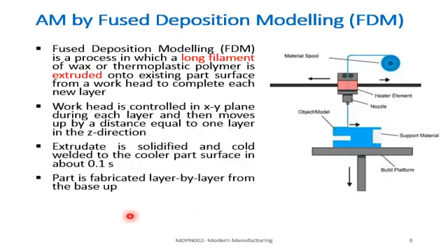The third process, which you have seen in the lab, in fact, is known as the fused deposition modeling approach. This is a very simple process, in fact. Here we have an extrusion head, and we have a filament, wire-like, of thermoplastic material, and then it goes through the extrusion head, and it creates a layer.